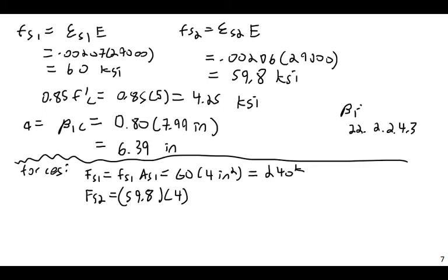I'm going to calculate the force from the Whitney stress block, so this is not actually correct. I'm just going to do that as the depth of the Whitney stress block times the width of the cross section. If I do that, though, I'm going to be double dipping, at least in the area of the compression steel. I would basically be saying in my calculation that there's both concrete and steel at the exact same location, and we know that's not possible.